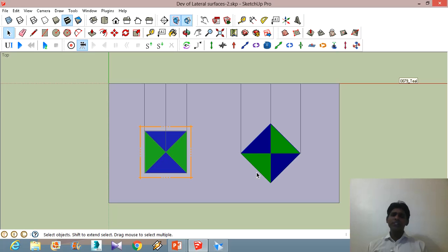Also, this is the position which we will use, that is in projection of solids, to rest a pyramid on the corner of the base, and this is the position which is used to rest this pyramid on the edge of the base. But in development, we will see what is the importance of these two positions. Let us see the front view. This is the top view of the pyramid. This orange color is nothing but the cut section, which I am going to use now.